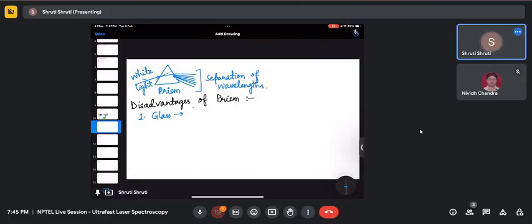Okay. So this question is about, in order to get a good spectrum, speed of acquisition should be fast, averaging time should be long, slit width should be small, concentration should be extremely high. So there are many factors we have to take care of in order to get a good spectrum. Considering only one will not work. So suppose the first one is scan speed. Scan speed means how fast you change your wavelength.